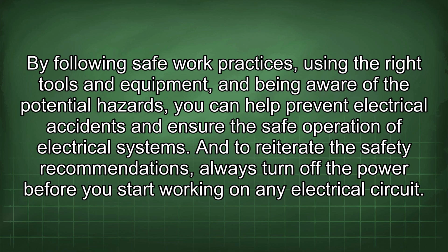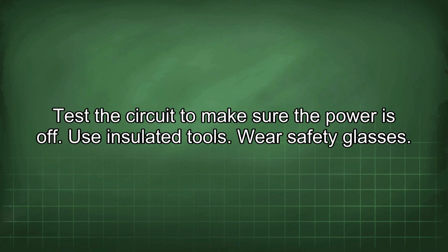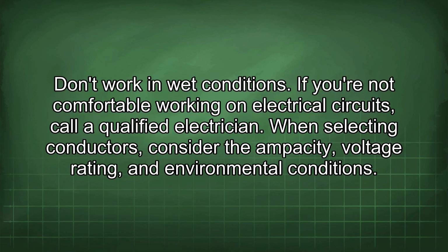And to reiterate the safety recommendations, always turn off the power before you start working on any electrical circuit. Test the circuit to make sure the power is off. Use insulated tools. Wear safety glasses. Don't work in wet conditions. If you're not comfortable working on electrical circuits, call a qualified electrician.